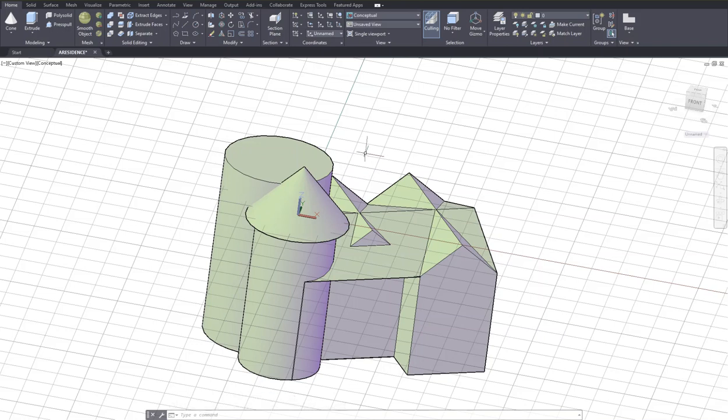And finally, the second one has to be done, and I'm going to move my UCS again. I'm typing UCS as I did in the first one. And now computer is looking for the start point, center point of the cone. I'm going to type CEN for center. This is a different kind of object snap. There are two kinds of running mode object snaps and